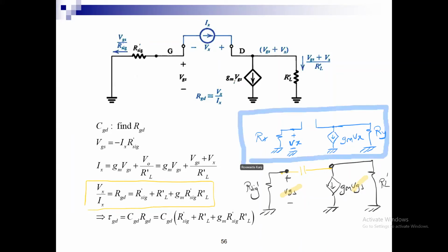Rxy. And for this rule of Rxy, the effective resistance seen between those two nodes is Rxy, and Rxy is going to be Rx plus Ry plus GM times Rx times Ry. Okay, يعني Rx plus Ry plus GM times their product.